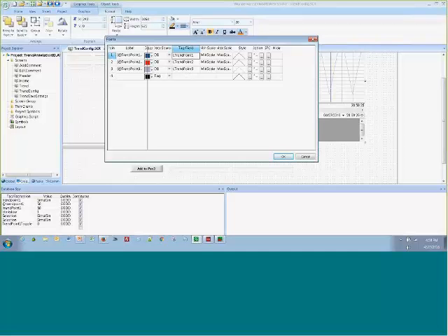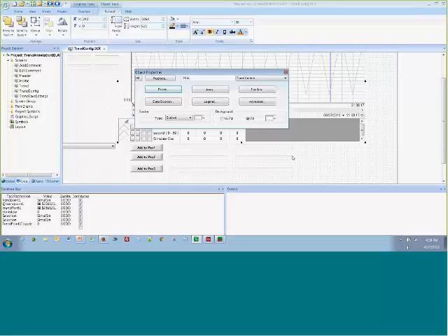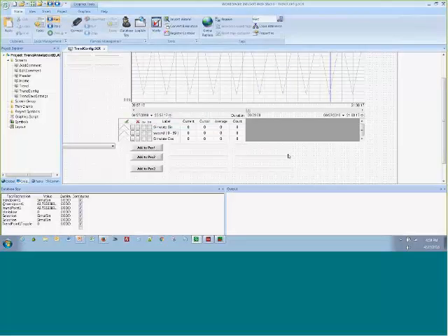I'm also using the tag property called description, indirect to tag trend.1, and then using this little syntax here to point to the description to automatically get that label in there as well. Same thing with the max scale and min scale as well. So really good ideas, really neat ways to use trends. So good point. Thank you for bringing that up, but I was already headed there, so I beat you to it.